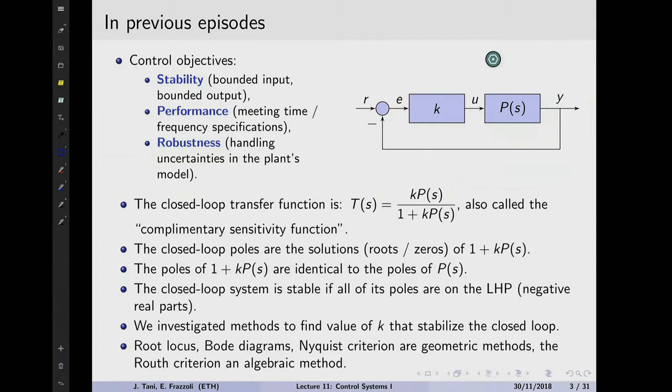That is, that part of the output term that we kind of neglected up to now. And we said, okay, so this depends on the poles of the closed loop system. We care that it's stable, that the real parts are negative. But then we kind of left it at that. But actually, shaping where these poles are determines what are the properties of the response in the transient, so at the beginning.